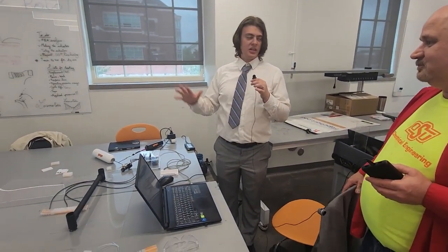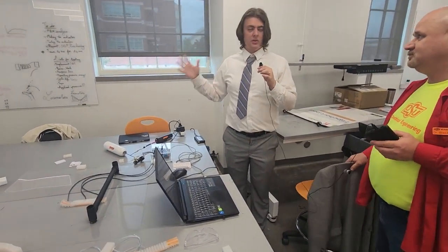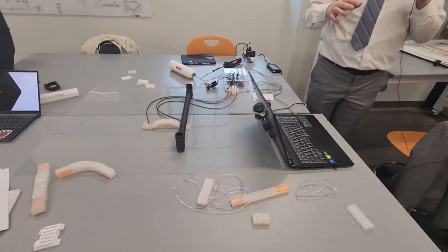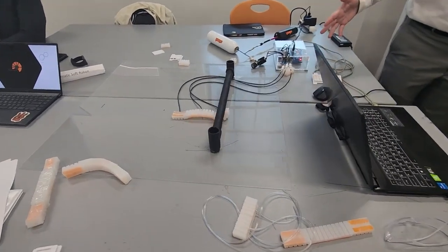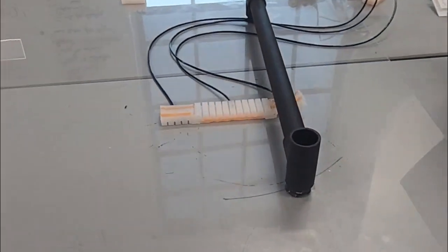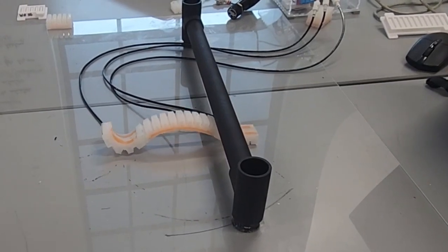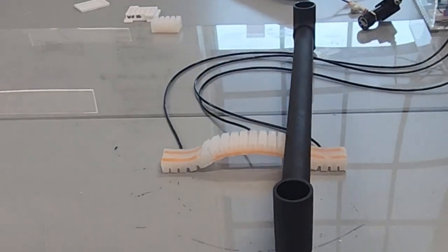This is all done in the ATRC, where we use a vacuum chamber to degas our silicone to try and get all of the bubbles and imperfections out of it before we pour it into a mold, where we let it sit for about an hour or so, and it's ready to go. We just have to put a base on it, and we can start moving it.